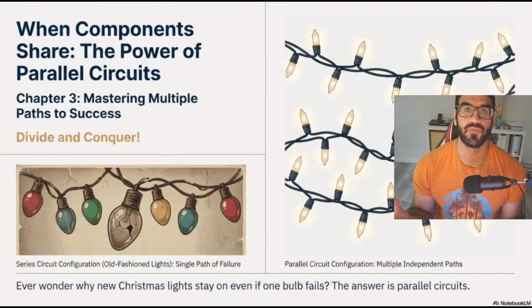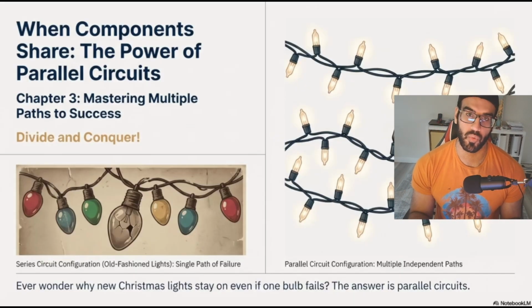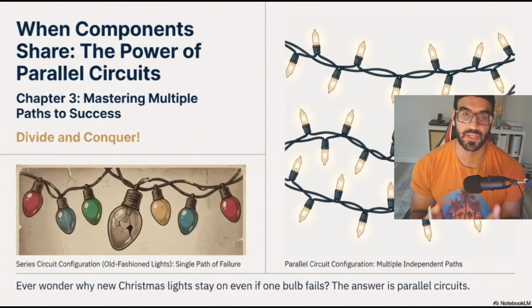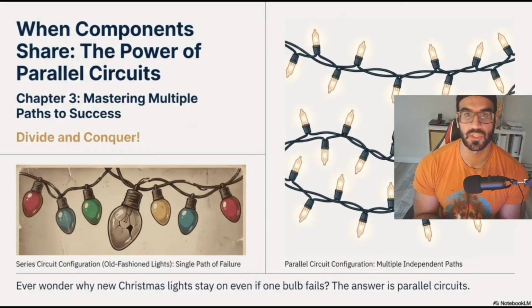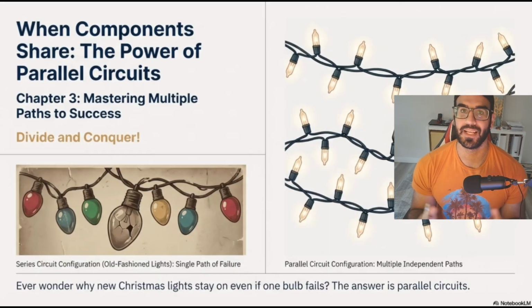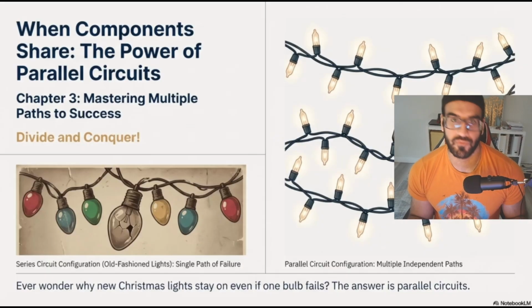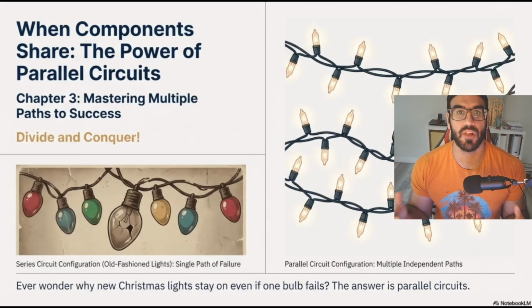It means that all of these components are connected side by side and the current that goes through one component is the same as another one, and totally the same as the total current. So we had a little bit of a problem with those kinds of circuits. Despite the fact that they were good, they had an issue: they cannot handle even one smaller, teeny tiny problem with one of the components. If something happened to any component like a resistor or some kind of diode, everything would collapse,